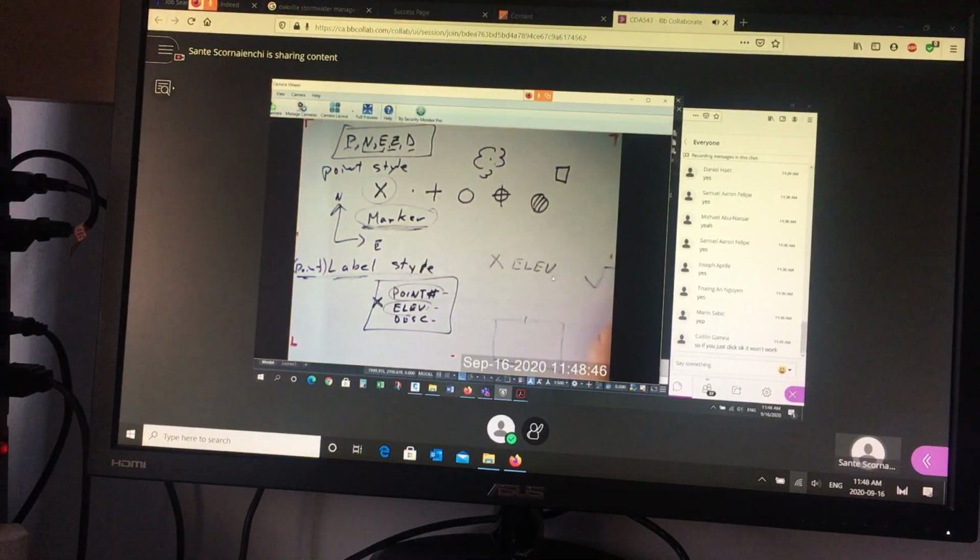When you talk about a curb and gutter, they want the elevation of the gutter and the elevation of the top of curb. So in the plan view, you always need 2 points. What's this elevation? What's this elevation?